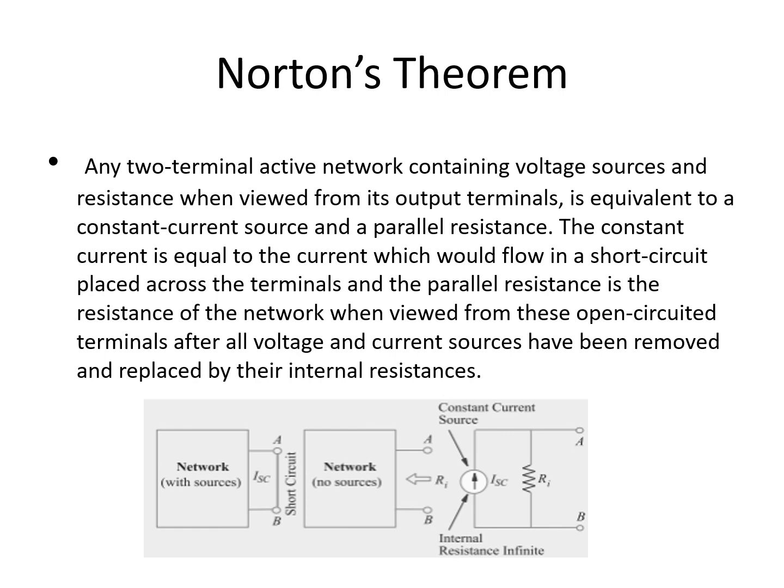Now it is a short circuit current in parallel with an internal, infinite resistance. Some books call the short circuit current I_NT to specify Norton's, and the resistance R_NT, or the Norton's resistance. But this R_NT here is just equivalent to your R_TH. How we solve for R_TH in Thevenin's is the same as how we solve for the equivalent resistance in Norton's theorem.